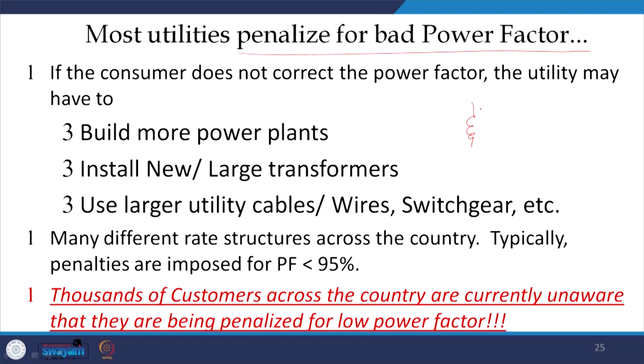So, you generally have an inductor with thyristors in parallel, so you can bypass this inductor, or you can allow the current to flow through this inductor. Thereafter, you can have a capacitor.